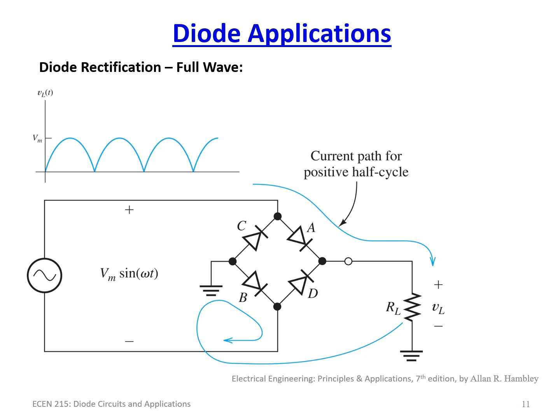And obviously the output here is this humped version. So it's not exactly DC, right? It's got these humps. So how would you get rid of these humps? What you would do is you would put really big capacitors out here. A bank of them, actually. Something in the neighborhood of probably about 2,000 microfarads, or maybe even a little bit more. And what would end up happening when you did that, you would end up with a fully DC signal.